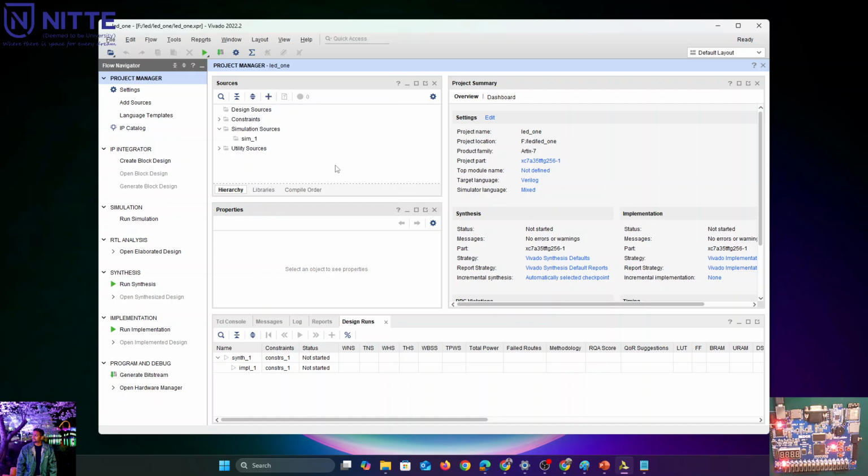As we already know, the basic difference between a microcontroller and an FPGA is that in a microcontroller we just focus on writing the embedded C code, whereas in the FPGA we need to do that as well as write code to design our custom hardware based on the FPGA IC. So to write the code, we need to create a .v file by using add source.